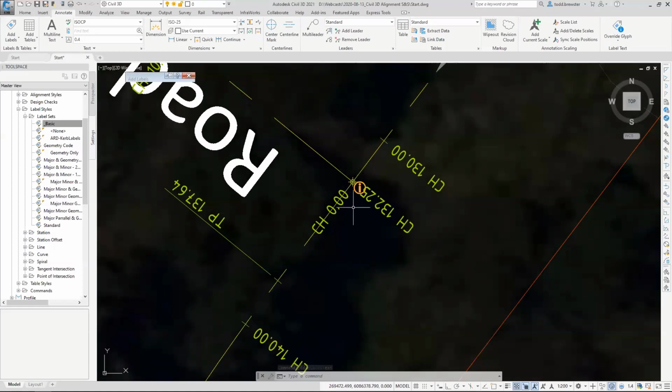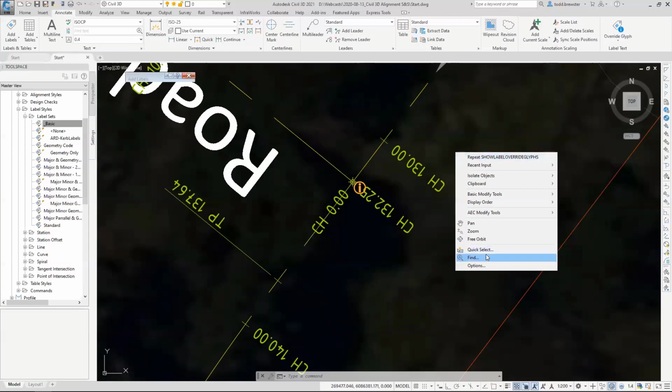But that is just a single application of that. The next time I use that label, it will still be 3 decimal places. You also get this glyph override warning. If you're on the annotate tab, you can use this function here to hide it if you don't want to see it. It's a non-printable character, but it can be a bit annoying, so you can turn it on and off there. There's actually a function, this is another big tip. You can turn them off globally.